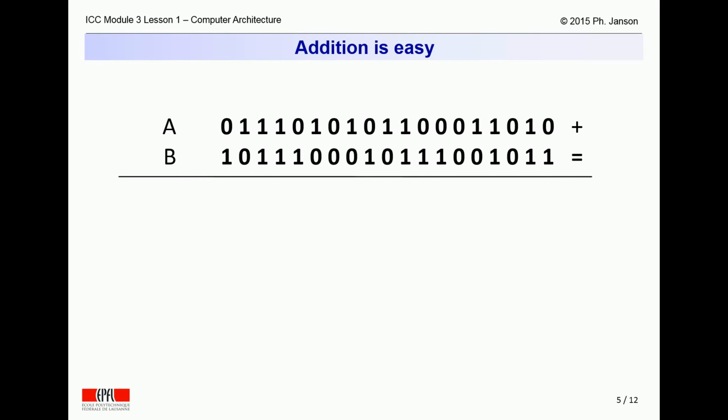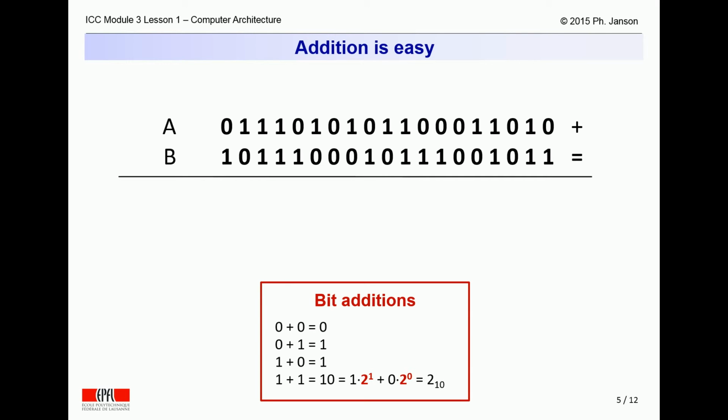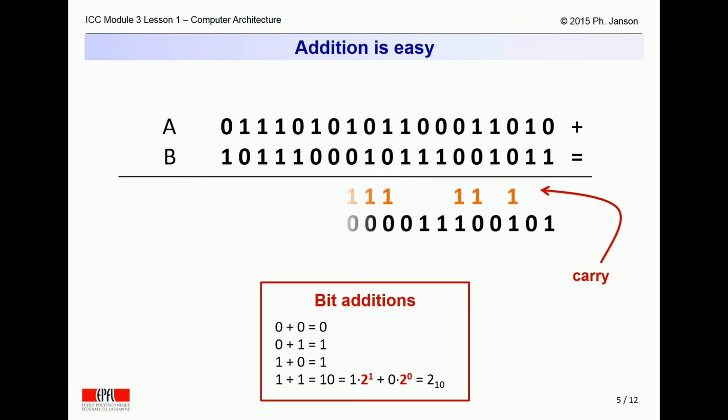Consider, for instance, how one can reduce the time to perform an addition. In doing so, remember all possible 2-bit additions, observing that if both bits are 1, then the result will include a carry bit into the next order addition. A basic adder starts by adding the two lowest order bits, then proceeds to add the next two lowest order bits. It cannot proceed faster because at every stage it must compute the carry bit before it can compute the next stage. Only then can it move on and on to the highest order bit.